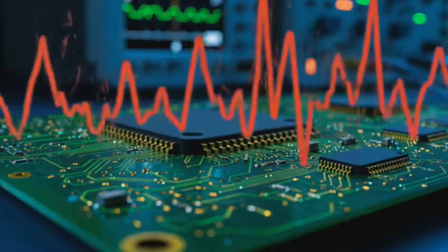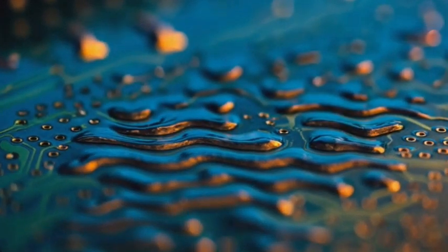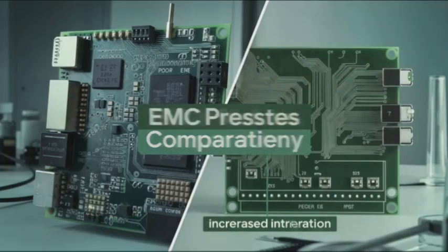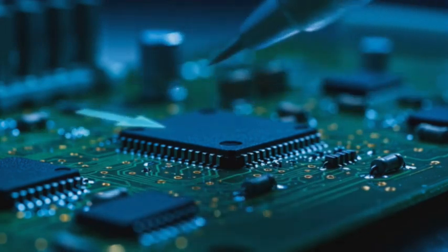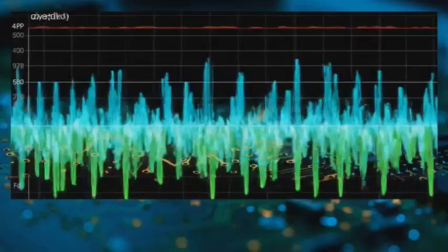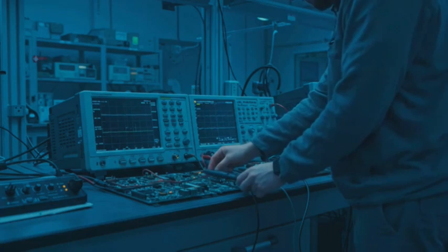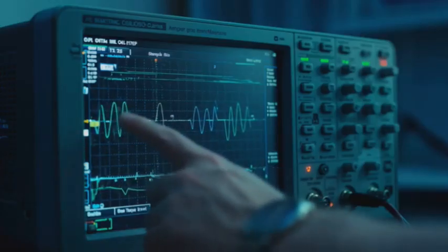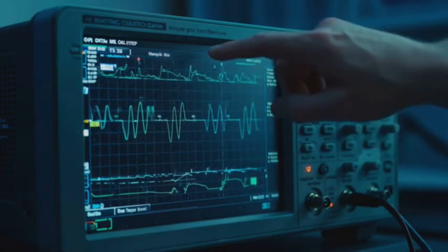Rapid switching transients from digital signals and references typically create noise. Good EMC practices include continuous ground planes, proper decoupling capacitor placement, minimizing overshoot, and isolating sensitive analog signals. We conducted experiments comparing layout techniques' impact on analog performance, RF emissions, and susceptibility. Another experiment series analyzed digital communications, examining trace spacing, grounding, and via placement effects on noise.